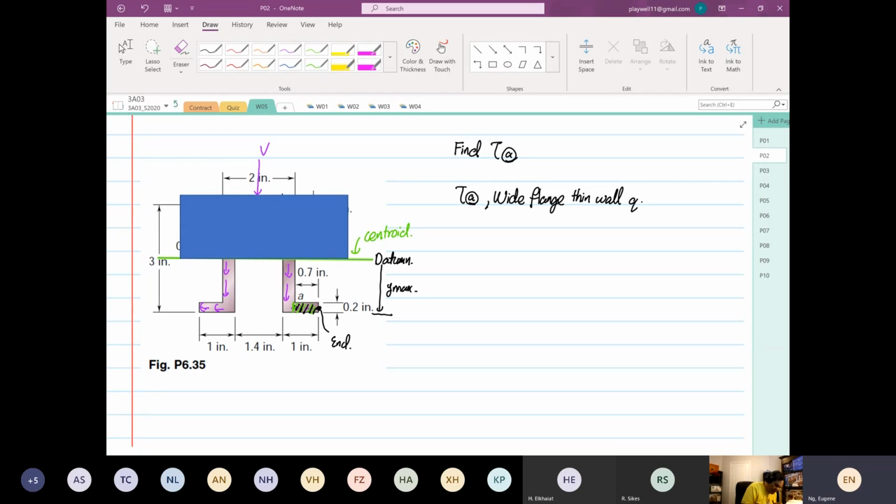Why? Because of the shear flow over here. Your Q1 over here, I call it Q1, and your Q2 on the right hand side. They do not initiate at the same point, and they don't end at the same point, so you only consider one side. It's not just where it initiates; it's where it ends also. It ends at only one point, one arrow. Q1 and Q2 don't end at the same point. That's why you only consider one Q.